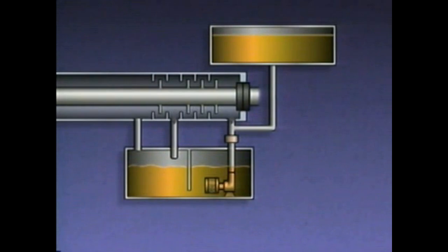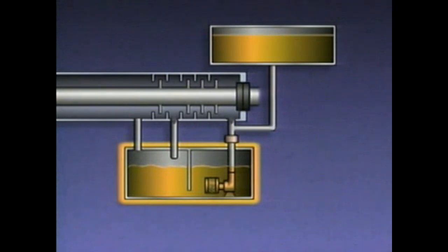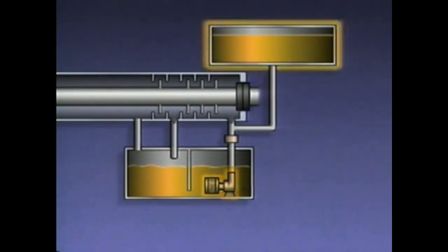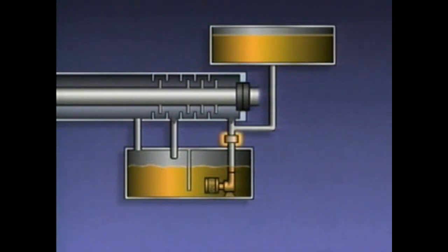Both mechanical seals and labyrinth seals may be used with a seal oil system. Some compressors rely on a seal oil system to prevent gas from leaking out of the compressor casing along the shaft. The simplified seal oil system illustrated here includes a mechanical seal located around the shaft at the point where the shaft penetrates the compressor casing, and a labyrinth seal. The seal oil system also has a seal oil reservoir, which is divided into two compartments. The reservoir contains a strainer and an oil pump. The system also has a head tank and a check valve.